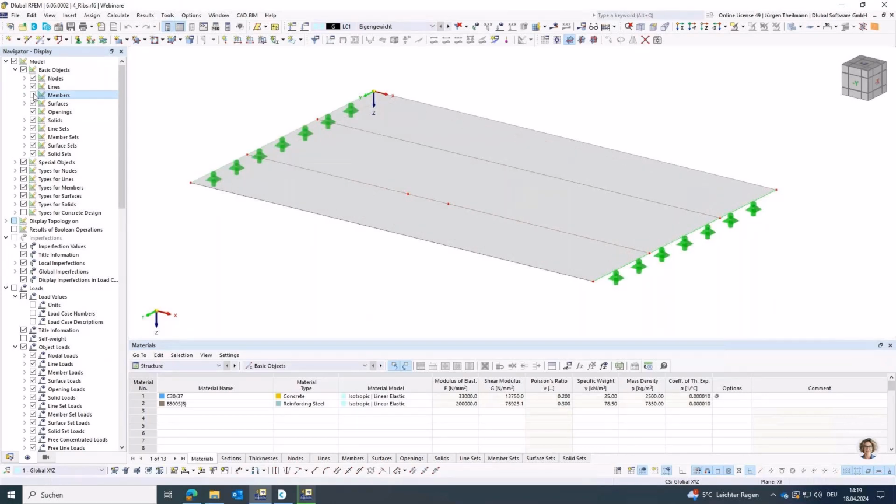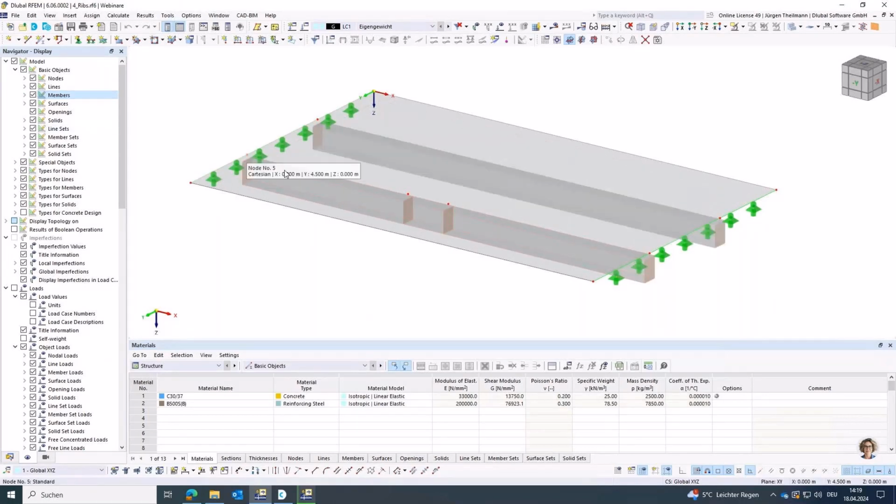And the problem now is with a downstand beam, which is a member of the type RIP. There is an inconsistency of the topology of the model when you want to have this downstand beam, which goes from node number 5 to node number 8, and the computer needs to calculate the effective width from which the surface internal forces are integrated into member internal forces when there are these 2 intermediate nodes